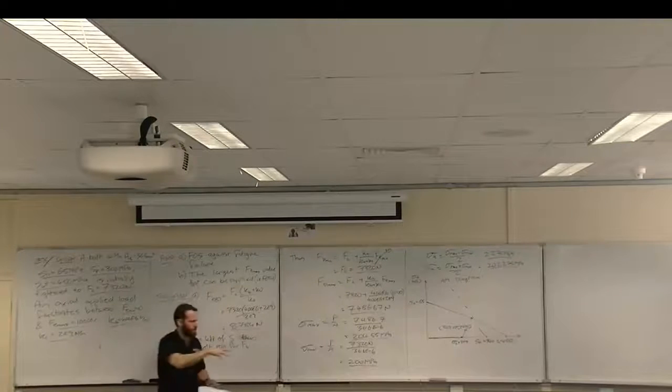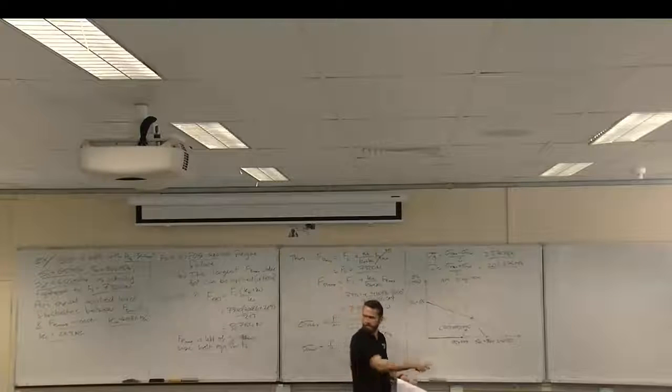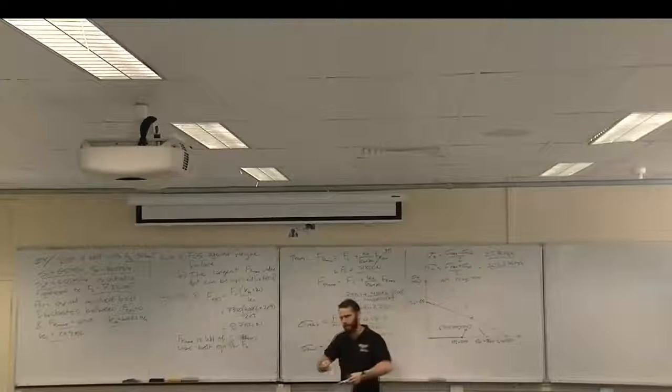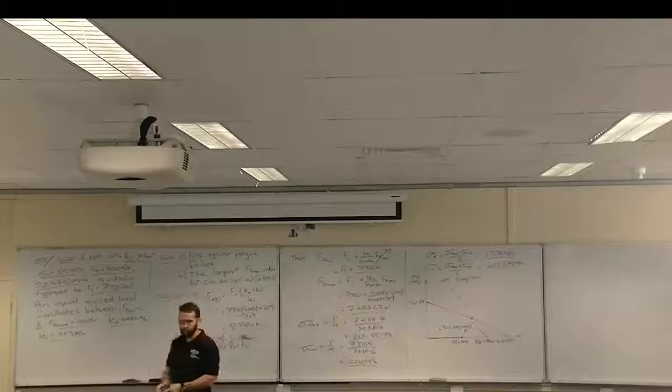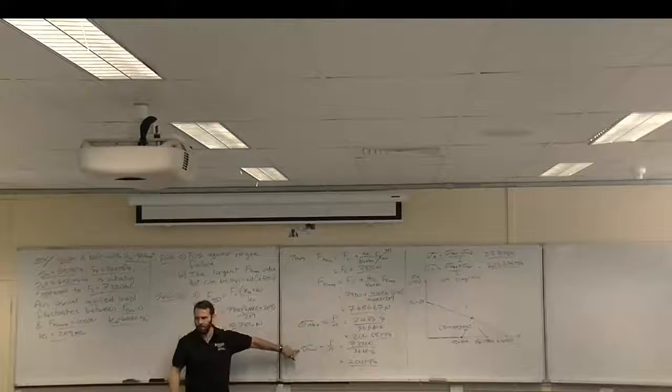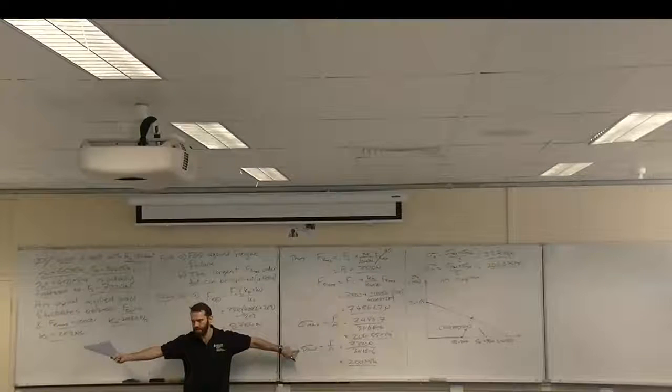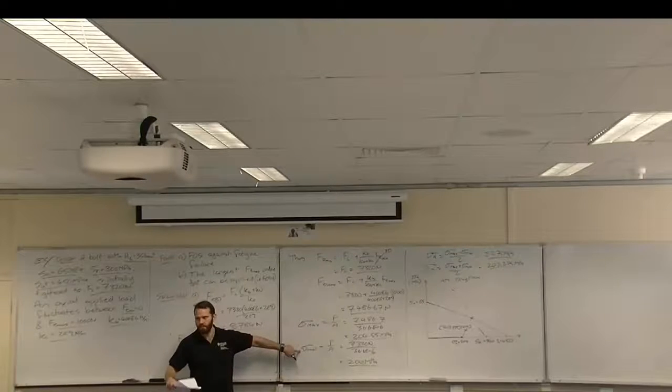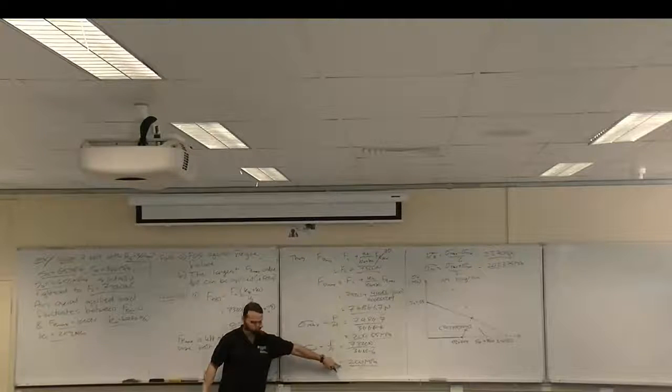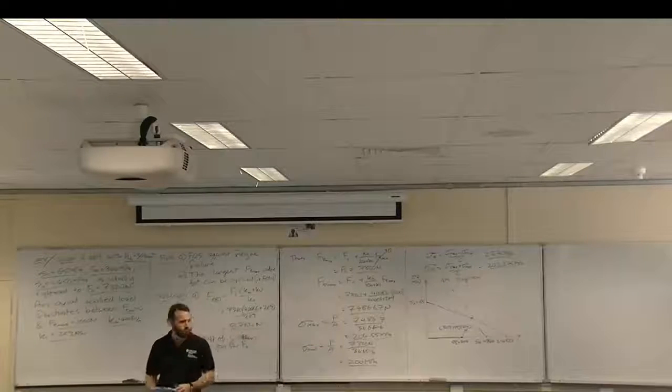Yeah, so that's whatever our pretension stress is. Alright. So whatever you tighten it up to in terms of stress, that's it. Which also just happens to be our sigma min. So the sigma min, if you don't have any applied stress, if you're going between 0 applied load and something, then our minimum stress is actually whatever we're tightening it up to initially. That's again the proof load. So if we knew the proof load, we wouldn't theoretically have had to calculate this, but we did just to go through the motions.